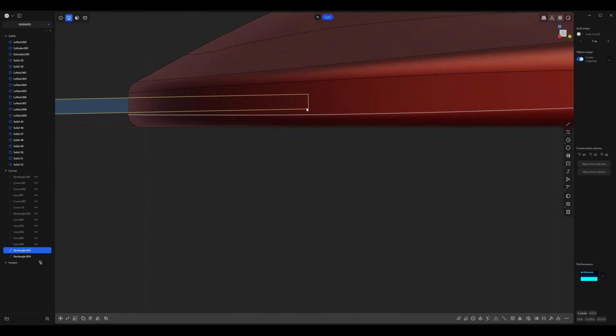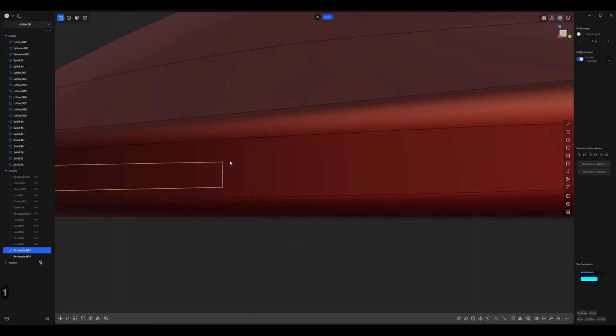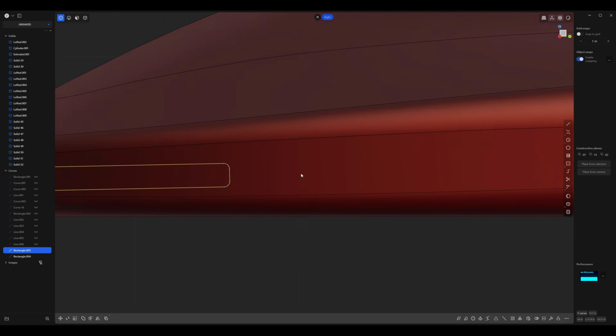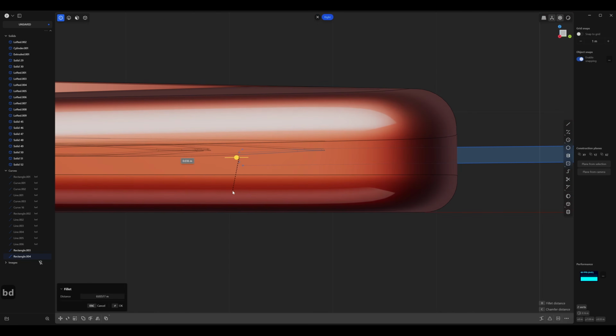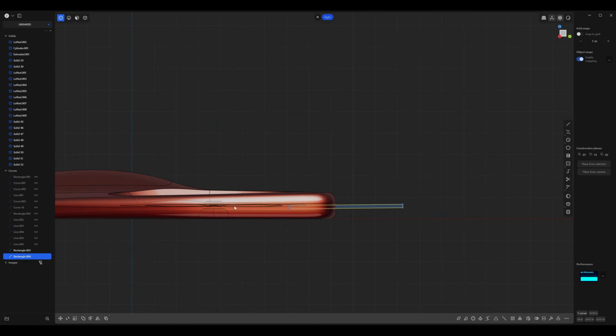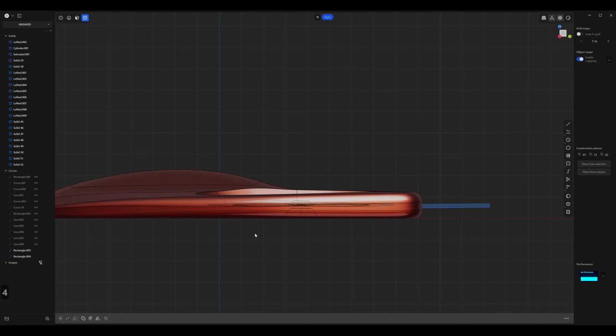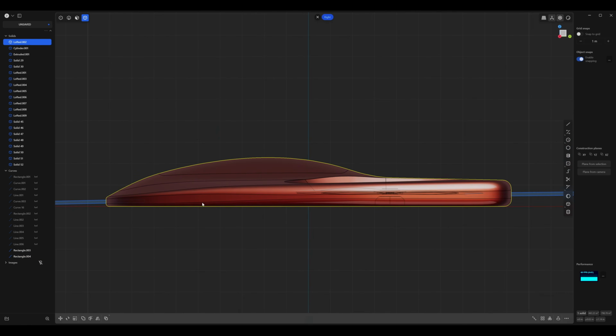And let's give this area a bit of a fillet. So press 1 on these points, press B and D, and now just hover it a little bit. Give it some rounding there. And let's repeat that for the back. B and D, hover outwards. Right click. Great, now press 4, select the main drone body, and then press C for cut.